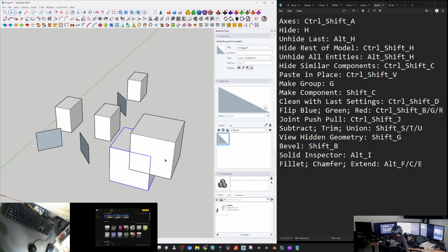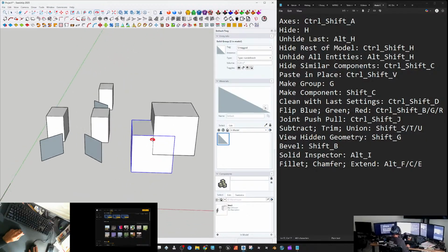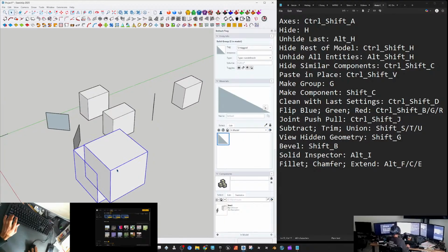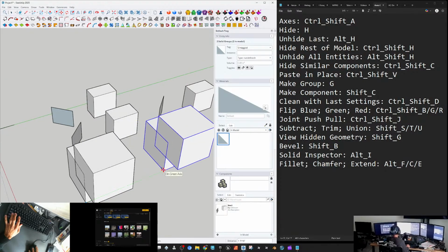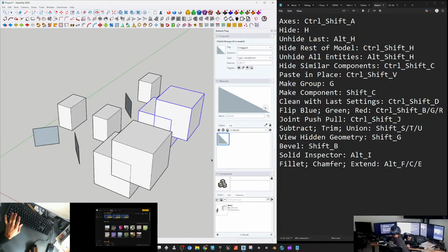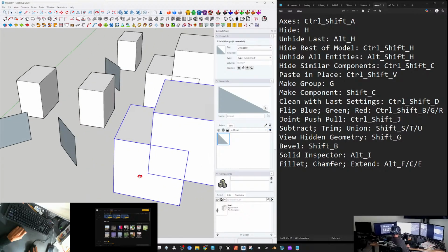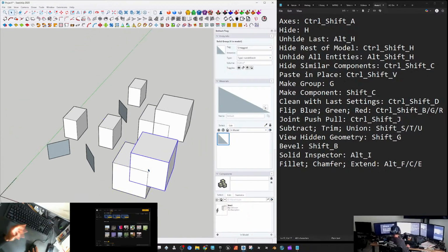Another thing to keep in mind is that when you press the space bar, you automatically go back into selection mode. So let me take both of these cubes, let's copy them over with move and control. So M and then control key. And then for one of these, I will select both. So the first one I want to delete is the one on the top. The second one, the one that I want to keep, is on the bottom. We'll do a Shift S.